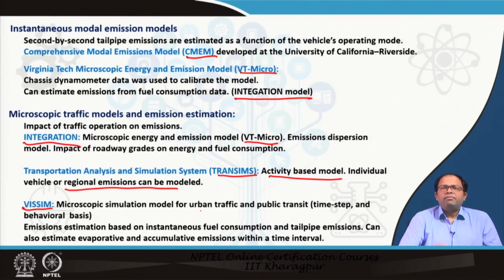Timely updates of how the vehicle is moves from one area to another, and also how the vehicle moves in the stream, are all recorded. Based on that, if we give the emission factors in this particular model, we can estimate the total amount of emission generated for each vehicle fraction. So emission estimation is based on instantaneous fuel consumption and tailpipe emissions, and it can also estimate evaporative and accumulative emissions within a time interval.